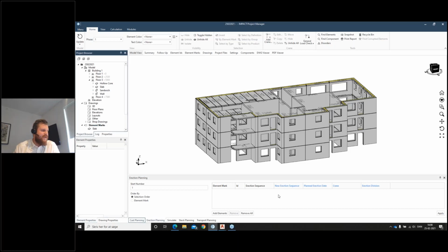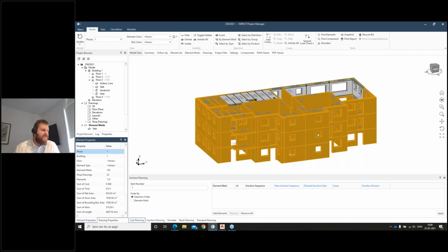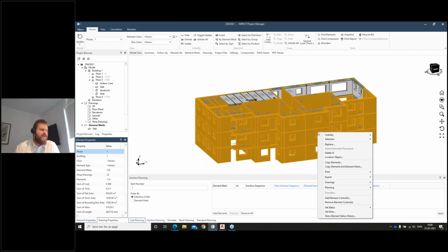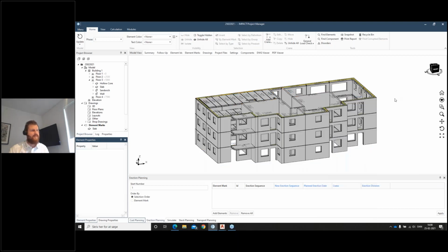So basically, we're getting all these drawings here. If I want to print out the drawings, you select how many elements you want to print. You go in here, you say drawings. Now I'm not allowed to print here, of course, because I don't have drawings on all of it. But basically, you press plot, and then you can print all of your drawings directly to your printer or to a PDF to send for approval to a client, for example.